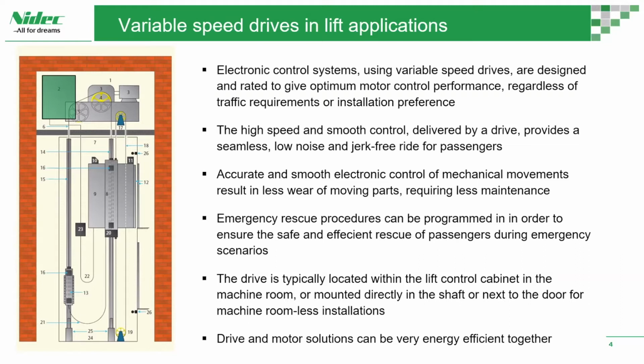So a lot of that braking energy, a lot of the energy that comes back into the system or is generated by the system, instead of braking it and burning that energy away as heat, with an efficient regen system on the drive, can be pushed back into the grid or reused by the system, saving energy overall and making the whole system more energy efficient.